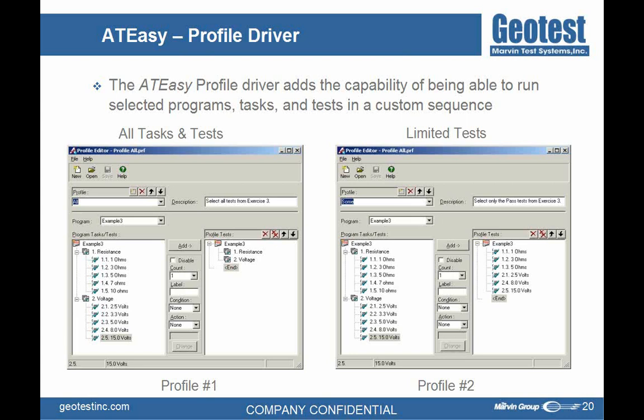The profile driver also allows you to associate user levels with the different profiles that are available. So an operator might have the ability only to run go, no-go tests, whereas a technician might have the ability to run diagnostics tests. So the profile driver gives you control of the sequence as well as managing user privilege levels to those different test programs.